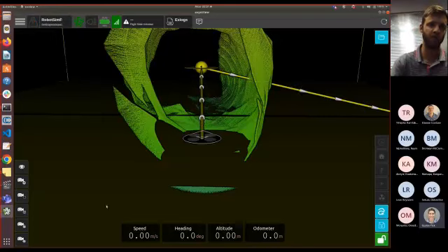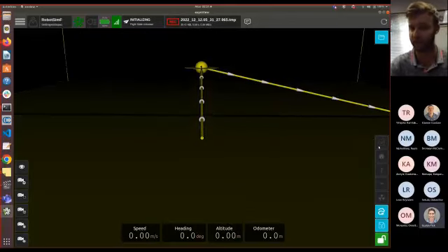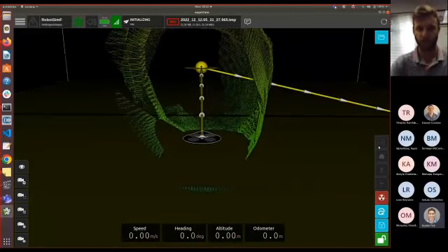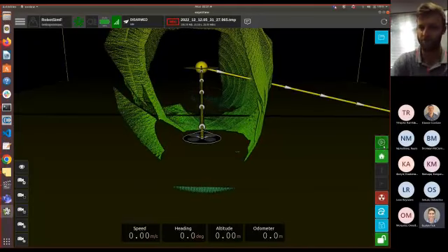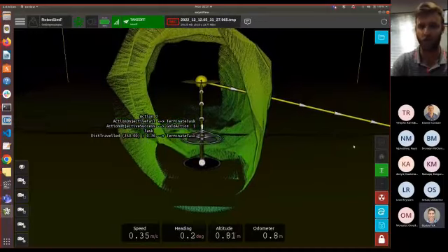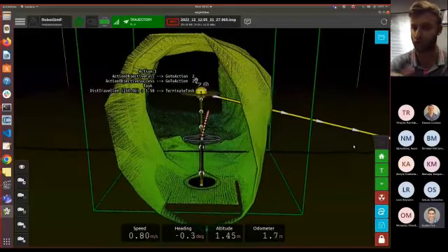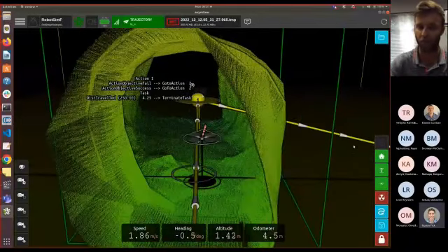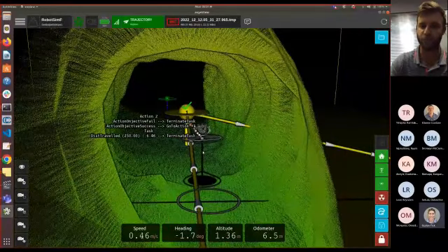So here we are. I'll start my LiDAR. And you'll see on the right that these grayed out icons, the top one is going to become green, and it's a play button. And that's really all I have to press to start my drone scan. So once the drone is initialized, I'll press and hold this play button here. And now my drone will take off and start its mission. So of course, you're underground. No one needs to help it whatsoever. You might even lose connection to the drone because it'll travel so far away. That's no problem. You can see the drone here is maneuvering, and now it's starting its explore mode mission.